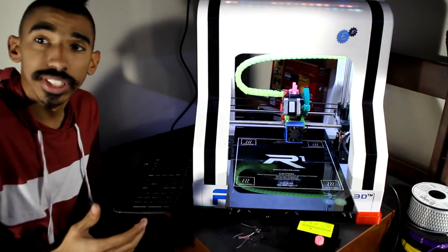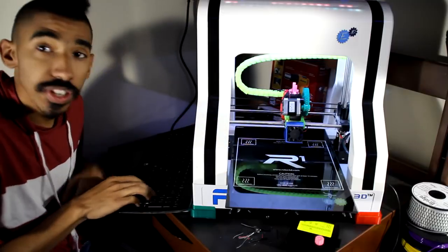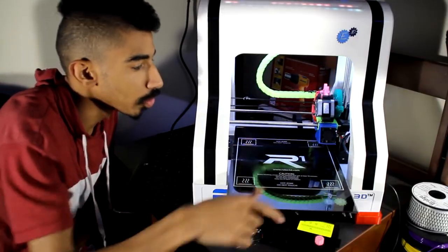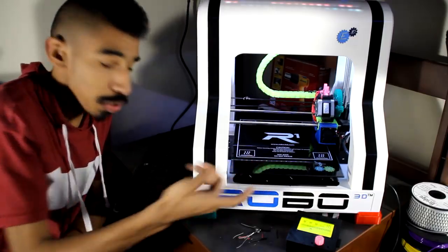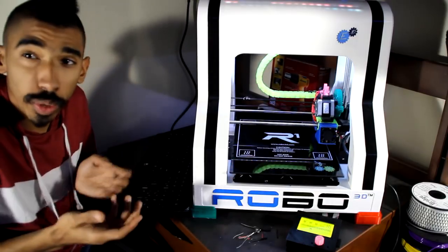At any point in time you need to work on something by moving the physical motors, run an M18 and you'll be able to move everything around. I usually don't use an M17 to re-enable the motors, but if you really want to, you can.